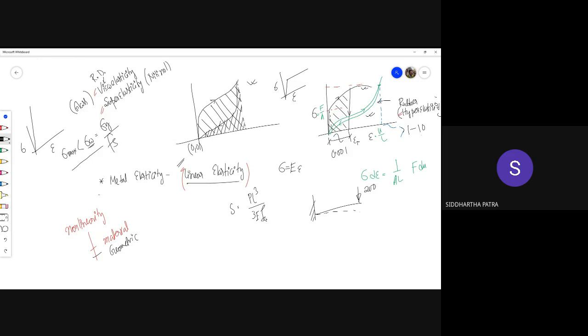Okay, and it doesn't change with P. It's just proportional to P. So the reason you have such a relation between force and displacement is because of two types of linearity. You considered geometric linearity. That means you didn't consider the change in the shape of the beam, number one. And number two is you considered a linear elastic material, hence the Young's modulus.